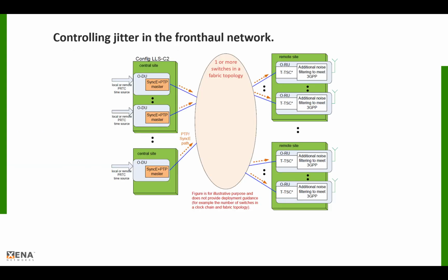The second timing consideration that's important when using an emulator in the 5G Fronthaul is the contribution of unwanted jitter by the emulator. The O-RAN S-plane uses PTP for timing synchronization, and it's known that the PTP protocol is very sensitive to jitter in the forwarding plane. Looking at the Fronthaul, it's clear that additional jitter will be added by every switch or network element that you add in the path between the DU PTP master and the PTP slave located in the RU. Further, a standard Ethernet switch, which is not timing aware, will simply introduce too much jitter for PTP to function correctly if inserted into the Fronthaul, due to the packet jitter caused by Ethernet packet switching functions like queuing, store and forward delays, etc.